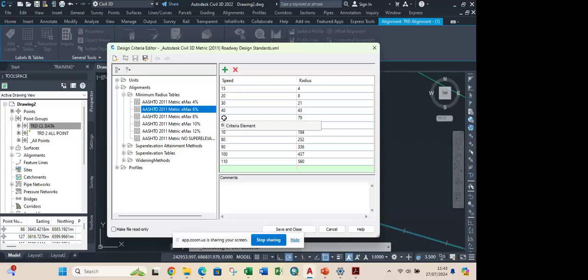So I'll put 50 before and after the curve. But I'll go less than 50 and put 40, so that the driver has room to decelerate, and if he's approaching at 50, he can still navigate. So I'll step it down by 10 kilometers. That's how it's done for your traffic management system. If I design a road for 60, you step it down by 10. That's the signage of the road.